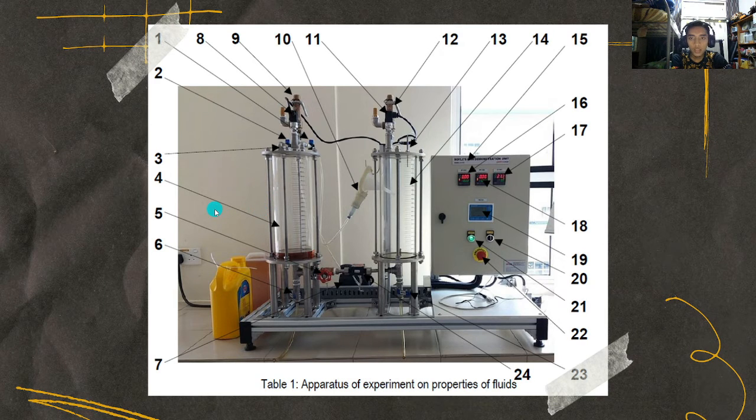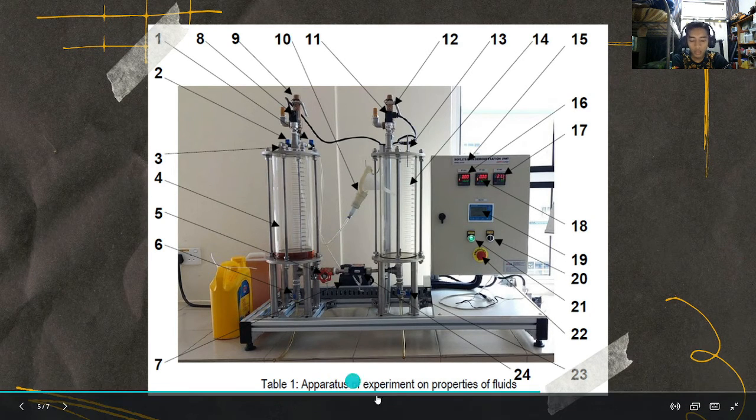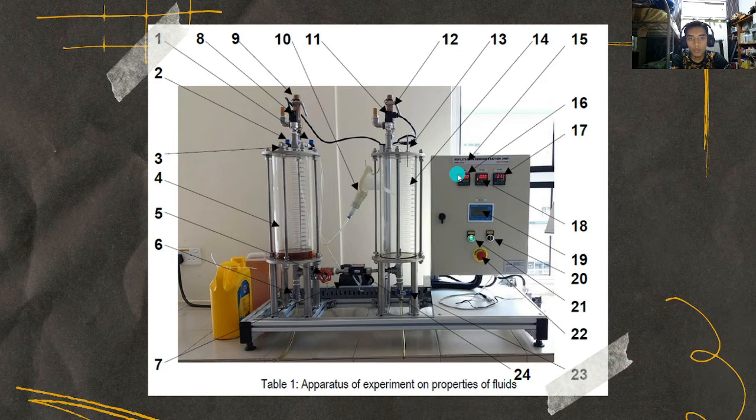For the shutdown procedure, we will ensure the pump switch is turned off and all valves are closed. So we will turn off all the equipment, and we make sure the valves are off: 1, 2, 3, 4. After that, if the tank is under pressure, we can see it at the pressure PT101. We will open BV102, the number 1, and the GV101, the red one. Then we will operate the vacuum hand pump P102 until both tanks reach 0 bar of pressure, and then we will close all valves.